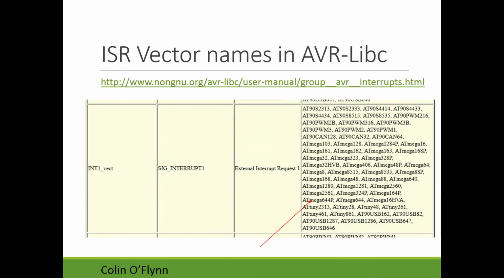The only caveat is that there's another link here to the AVR libc ISR vector names, the interrupt service routine vector names, and it's critical that you use these names. For example, INT1_vect has a column at the top listing which microcontrollers it's valid for. There are a few cases where there are similar-sounding names that are only valid for one microcontroller or the other.